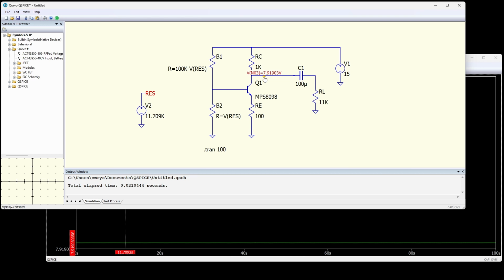So this is giving me the resistance for basically R2. I'm going to go ahead and replace this guy. Keep it named R2 to be consistent. And this is going to be a 10 kilo ohm resistor, because I don't have an 11.7K resistor. The closest I've got is a 10K or a 15K. So I'm just going to put a 10K.